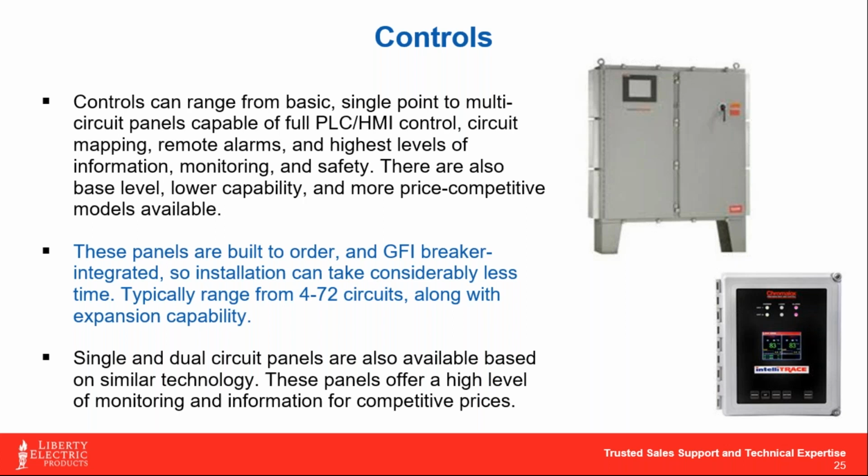You can put them into pretty crowded situations, and glean a lot of information off them too. The nice thing about these automated panels is that typically if there's ever a fault, it tells you what it is. And you can also get remote indication back to a BMS system, and so on. So these are usually a pretty good option from the standpoint that it cuts the labor figure down. The downside to the high-end panel is that usually they're a bit more finicky when it comes to power quality and things of that nature from within the plant.